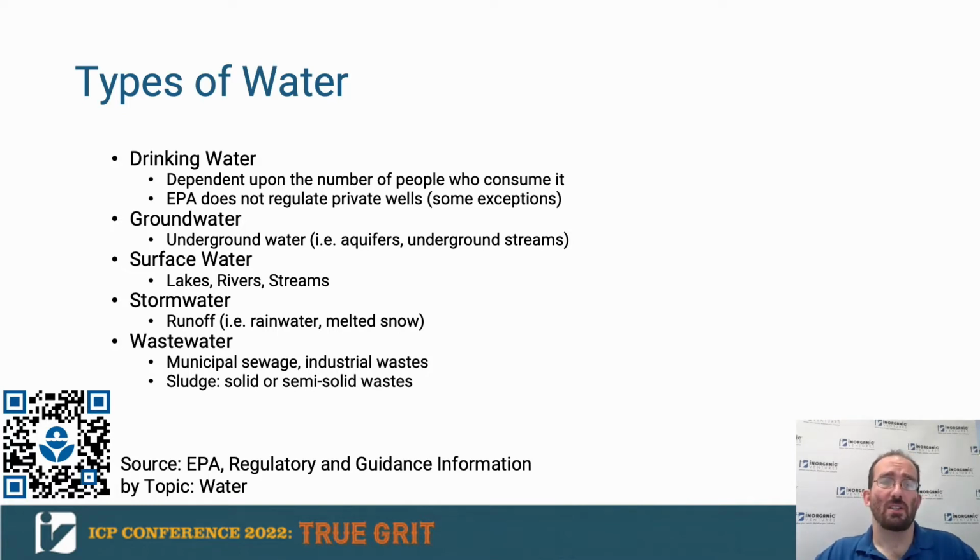The EPA is concerned about 4 different types of contaminants: any physical, chemical, biological, or radiological substance in the water. Basically anything other than a water molecule. A physical contaminant is a sediment or suspended organic material from sources such as soil erosion. Chemical can be either man-made or natural. Biological contaminations, which are slightly outside the scope of this presentation, and radiological elements that can emit ionizing radiation such as uranium or thorium.